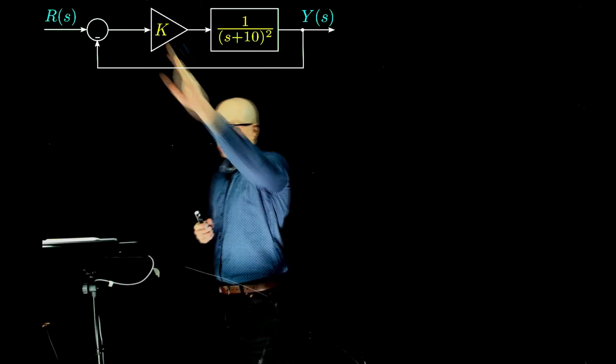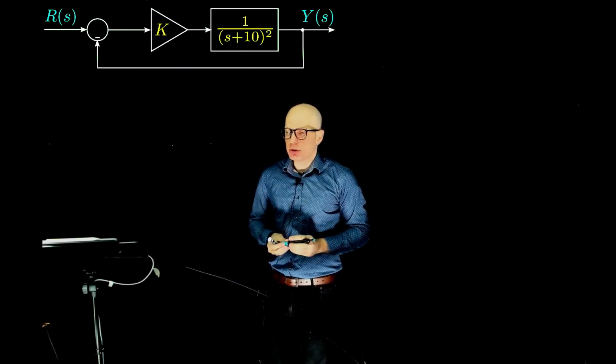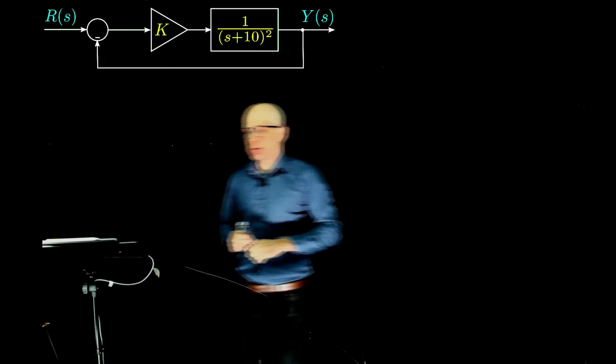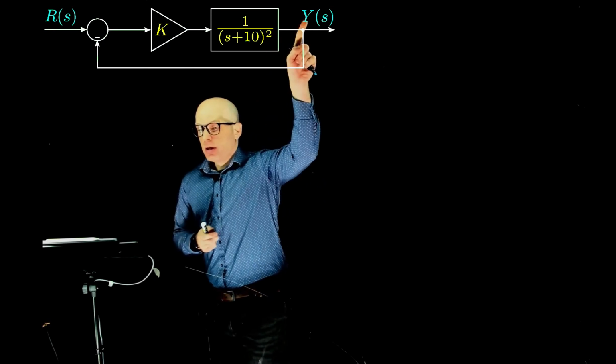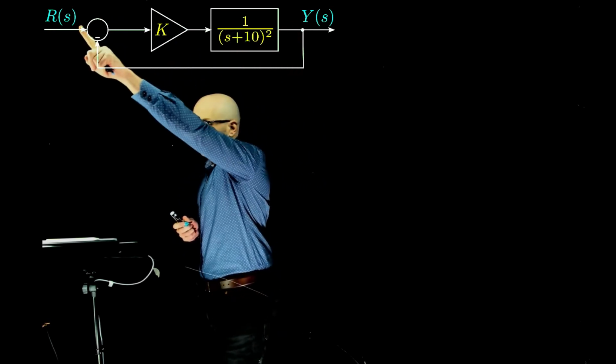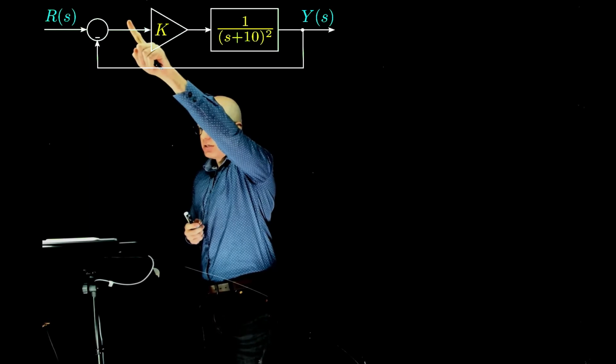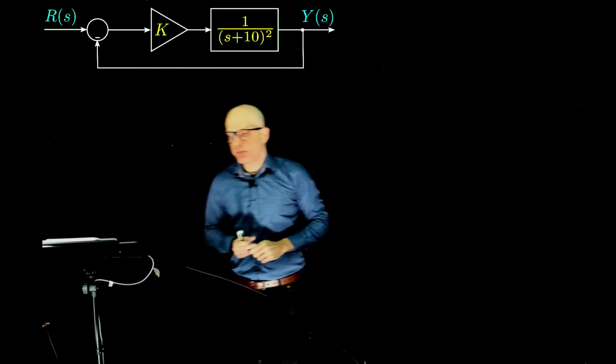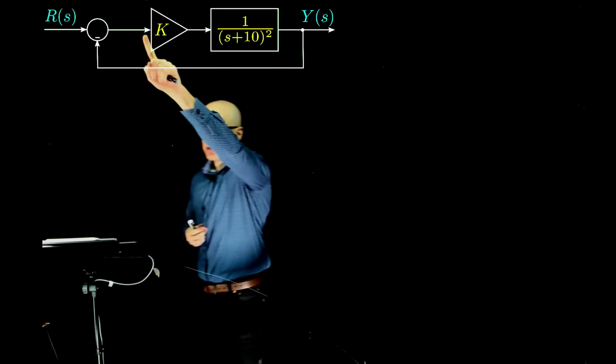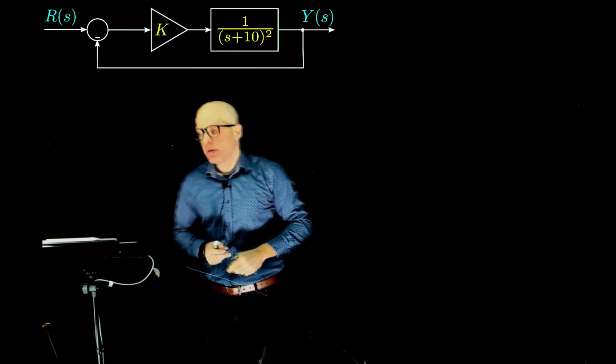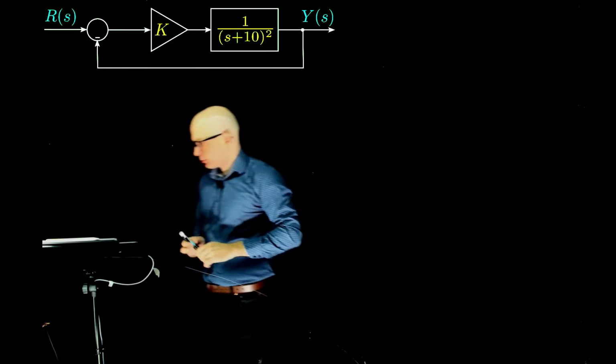Send that to the controller, and then the controller multiplies the error by a constant. So notice that when y and r are the same, this is 0, nothing is given to the body. And when it's not 0, then we keep injecting something until we reach that specific point.